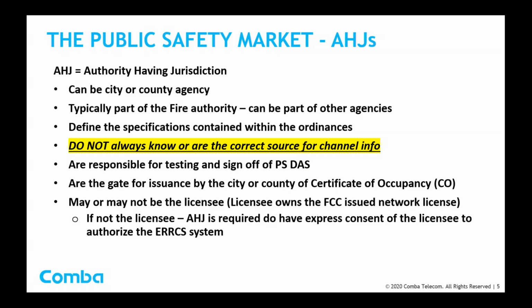And important to note, the AHJ may or may not be the licensee. The licensee is who owns the FCC-issued license for the network. And if it's the licensee, you are required to have express consent of the licensee to authorize putting that ERRCS system on the air.